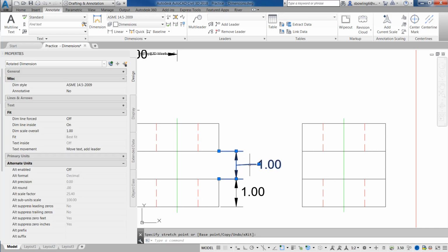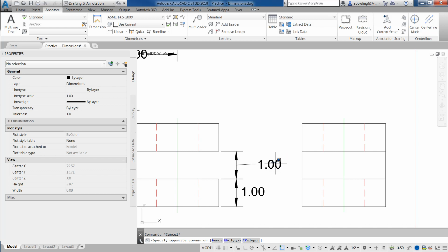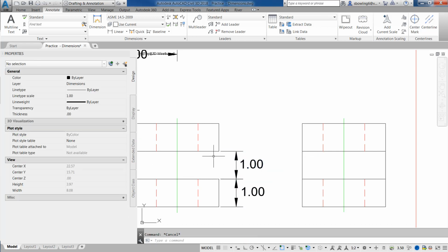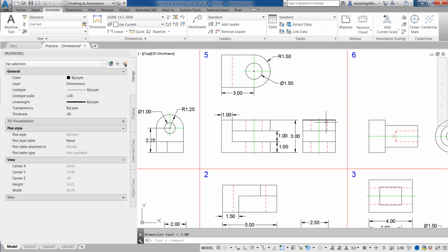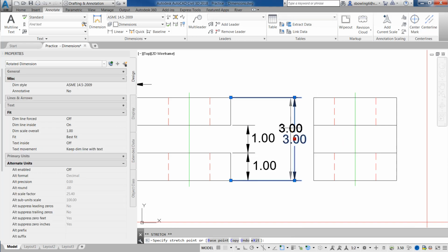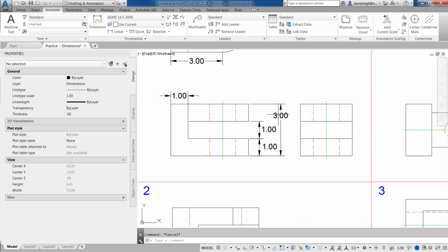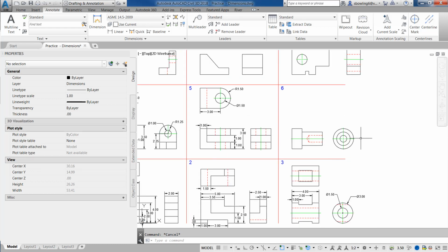I like to have these organized like this. So I'm going to change that to no leader and just pull these right next to it. It makes it look a little bit nicer. And then I'm going to do one linear all the way from here to here, and then pull it out to here. So you may need all of this scooched over a little bit more. Also, sometimes you can pull this up and stack it up here to make it a little bit more clean looking.